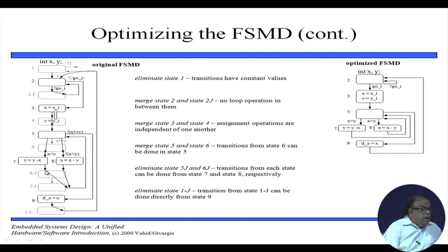And then I loop. Now, these transitions 6j and 5j that were there: from 7 I am coming to 6, from 8 I was also coming to 6j, but that is how it was written in the algorithm, and I can straightway merge them and come to this point. Therefore, this becomes a reduced state diagram.